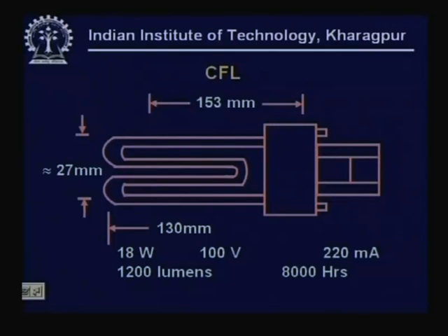The only objection with this kind of lamp may be that the envelopes have not improved to that extent, in the sense that, unlike a conventional fluorescent lamp, the light is not comfortable and the glare levels are high, and therefore, it should be avoided when used in a naked form. They are good if they are used together with proper diffusers. Also, when placed in recessed luminaires, that is recessed holders in the ceiling, they are very good.